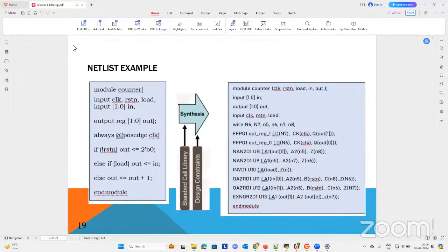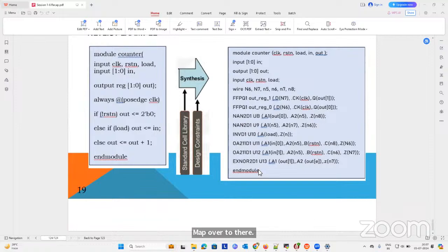So this is a practical example of Verilog code after synthesis, mapping to the technology library, and converting RTL to a gate level netlist. With optimization, we are getting this kind of hardware description language mapped to a standard cell library.